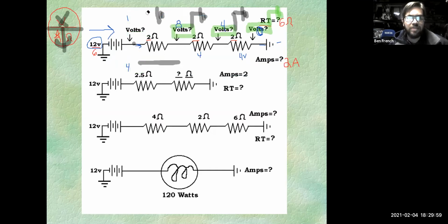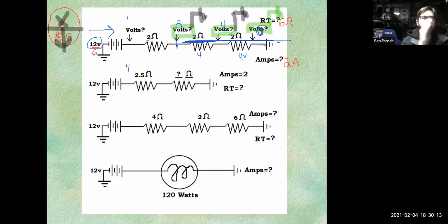This next meter, he's measuring the voltage drop from this point and then across all this stuff, because he's hooked between there and ground, right? And so you can see that's why the meters step down in different segments. So it really depends on where you put your meter leads.